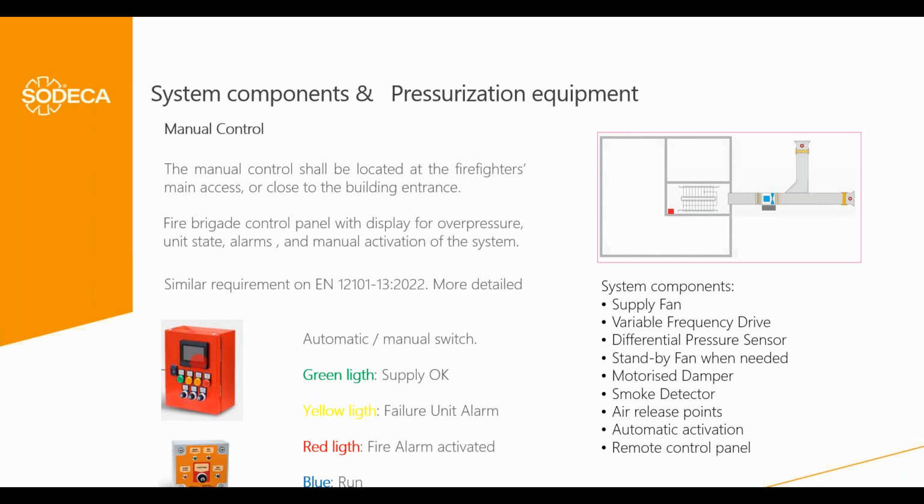with all the information. So when the fire brigades arrive, they have information about the operation of the fan, if there is a failure of the system, the state of the smoke sensors, their inlets; all the components can be displayed here. And this touchable screen is also used for the commissioning stage, because through this touchable screen we can make the self-calibration of the system.